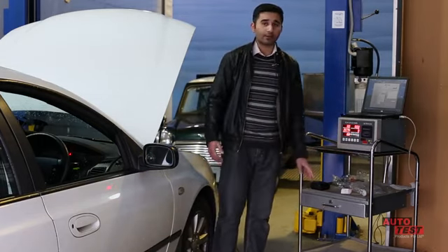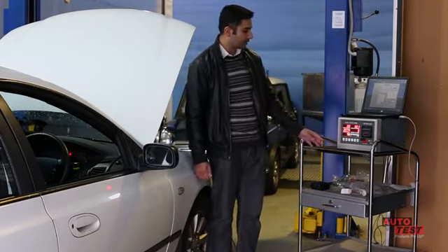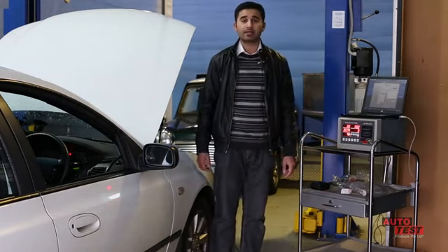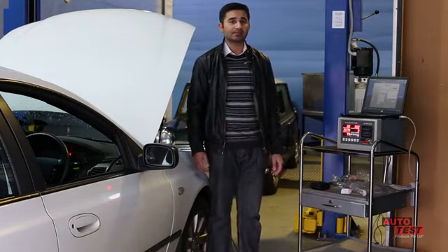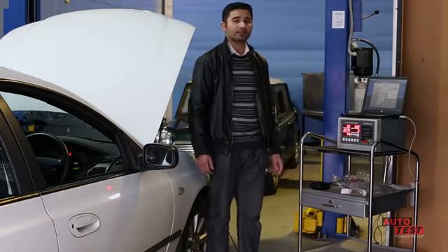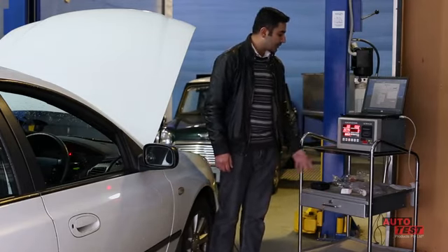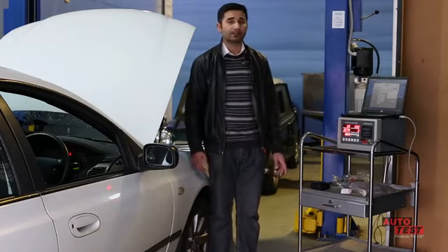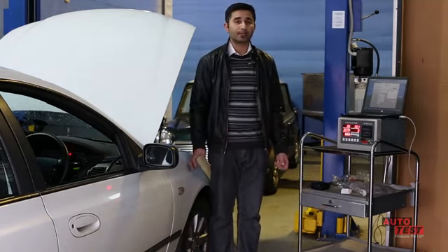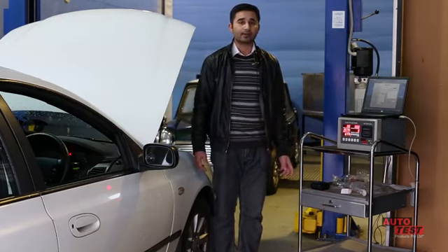Okay, now OBD2 is connected. We can verify and check the engine oil temperature. When we go to oil temp, it displays 76 degrees Celsius. That's the current engine oil temperature. We can scroll to RPM and see the current RPM of the vehicle. So this tells us that the OBD2 is connected and the communication between this car and the AutoGas is established and working fine.